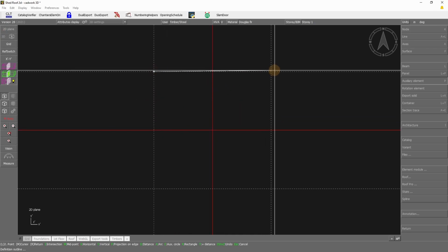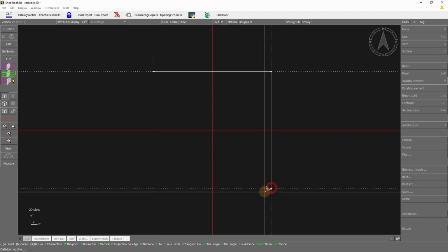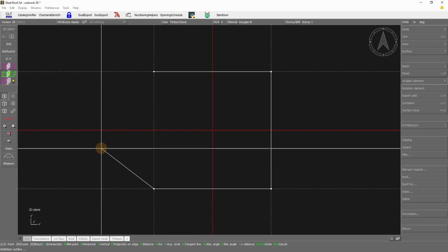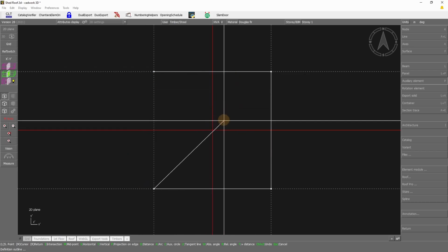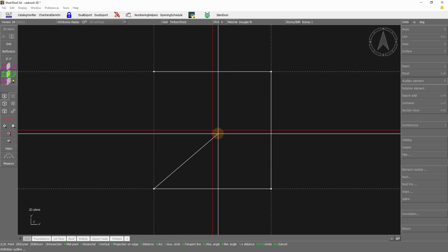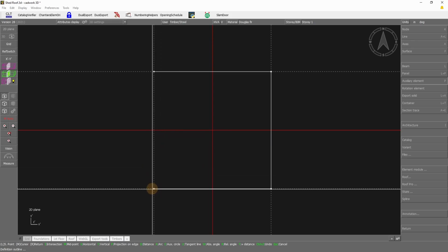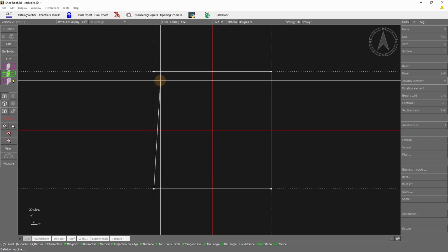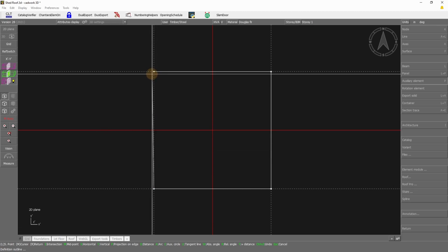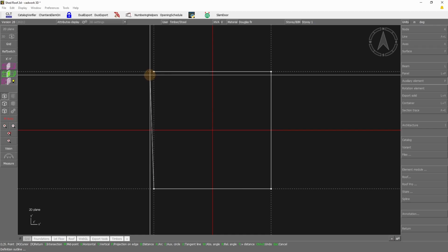And just draw the outline with left click using auxiliary line intersections. Just to remind you that when you draw a surface or a contour in Cadwork 3D and 2D, you do not need to click again on the first point you have selected, because you select corners and you are not drawing lines.